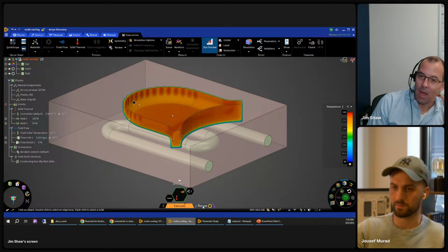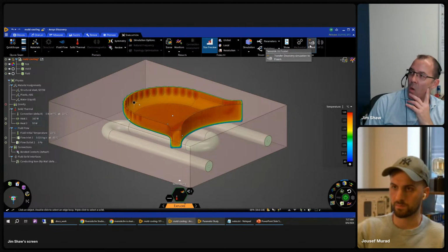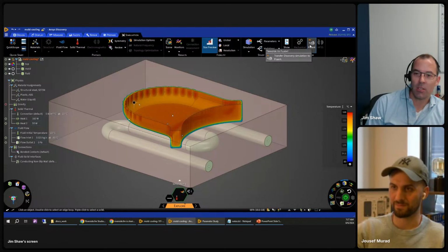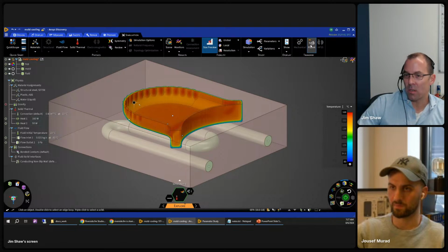And then level 4, because there's always another level, Yusuf, of course, is up here in the upper right-hand corner. If my comfort zone is Fluent, like mine is, if I know the tools in Fluent, if I want to add in things like phase change, multi-phase, all that stuff, I literally can transfer this straight into Fluent. I've got all my materials, all my boundary conditions, all my cell zones, if you will, and from there I can start to add in more and more detail.